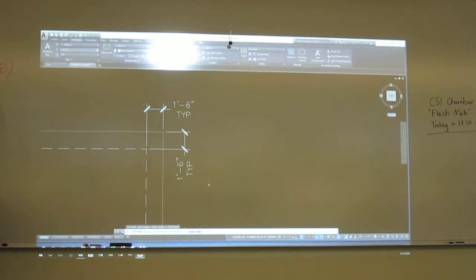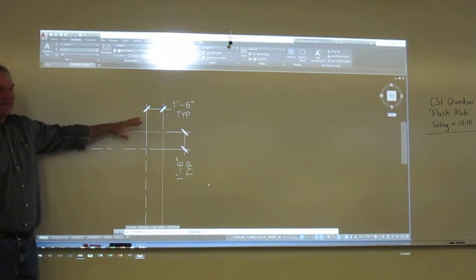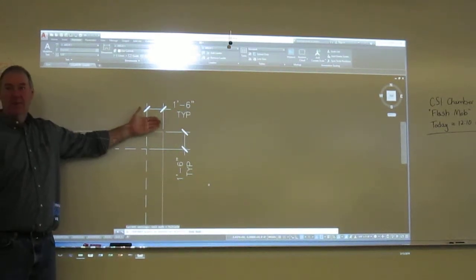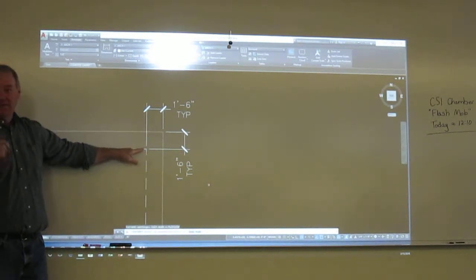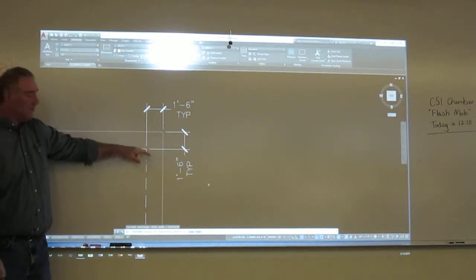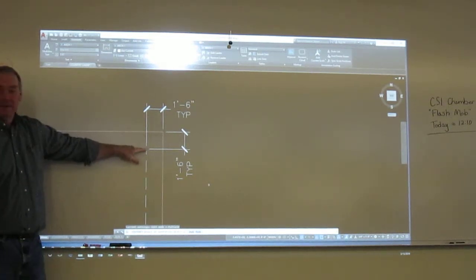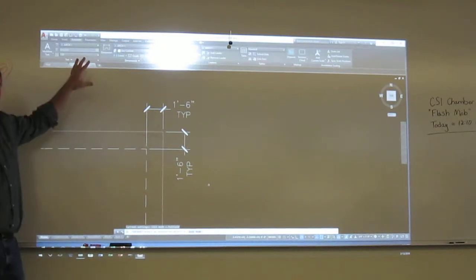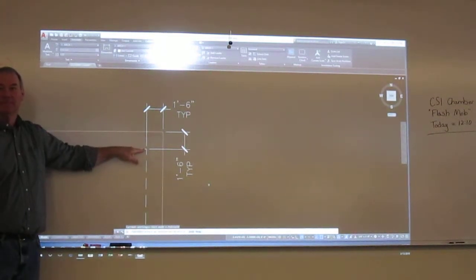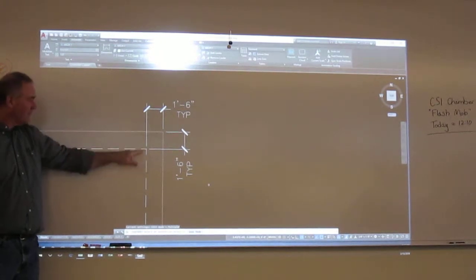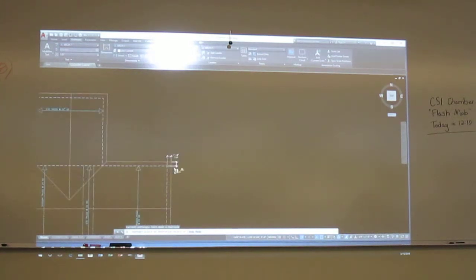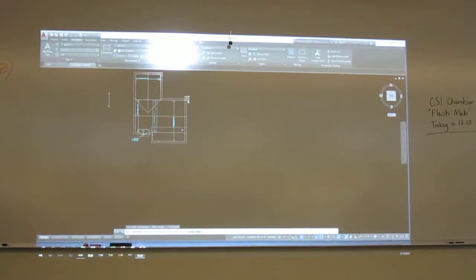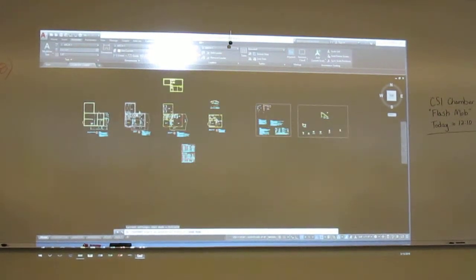If you had other dimensions, where there are eaves that change, you need to dimension them. Always dimension them. This is one case where you break a rule. One of the rules of dimensioning was never come from a hidden line, right? Here, you dimension everything from this wall because it's the only thing these roofers have out in the field to measure from as they build this roof. So you dimension from there. Now, you might have some other components. Okay, so that dimensions the entire thing, but let me show you a different roof plan.